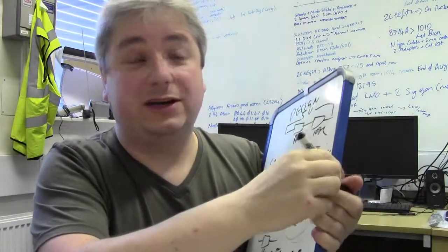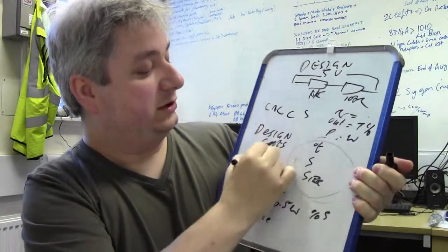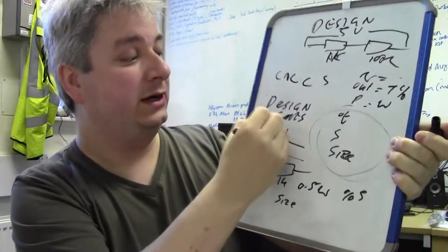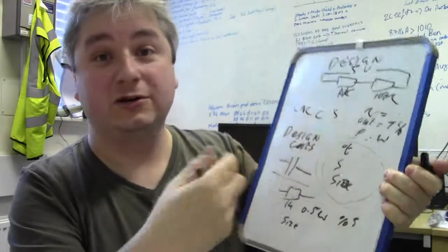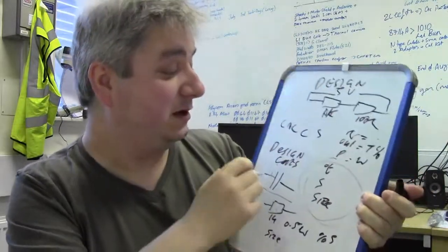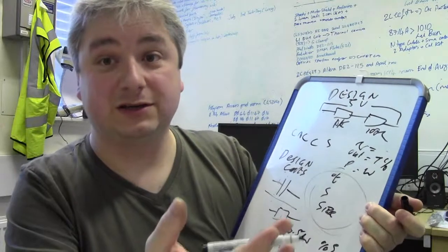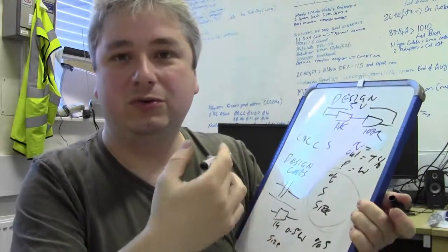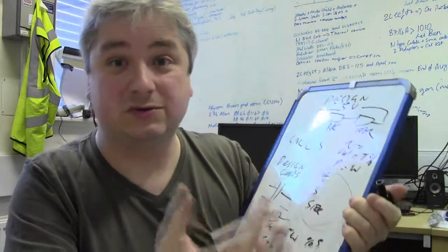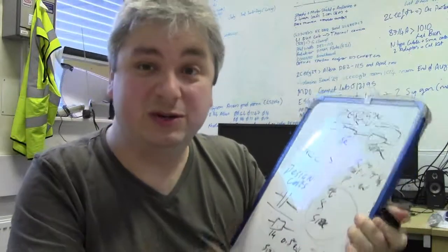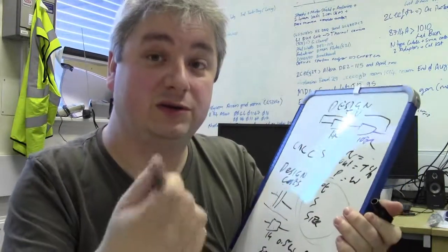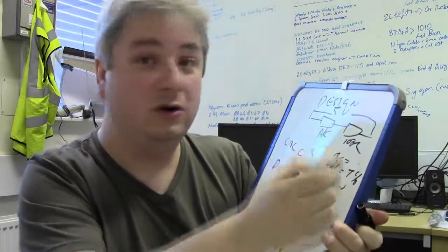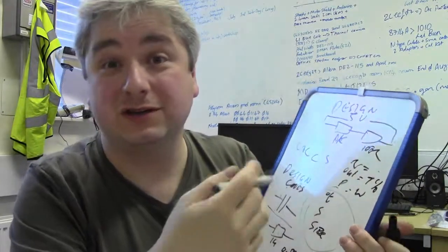But if you're in your lectures, you'll only see a capacitor which will look something like this, a capacitor. Well, you get polarised capacitors, your electrolytics, your tantalums and stuff like that. You get non-polarised things like ceramics, polyesters, micas, polystyrene. There's tons out there, all different sizes, all different pitches, all different voltage ratings, all different capacitances, all different types of materials, all used in all different kinds of situations. And you'll only work out which one you actually need by going out there, taking a look to see what is available, and also working out all the other calculations involved.